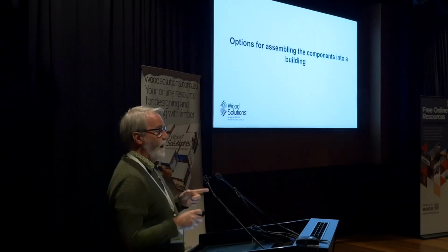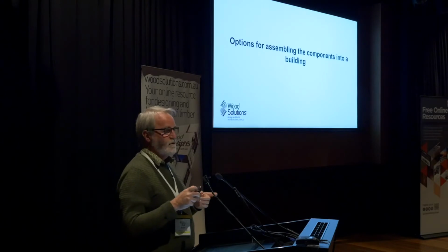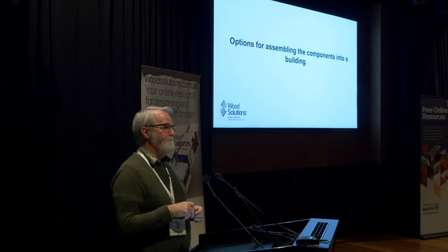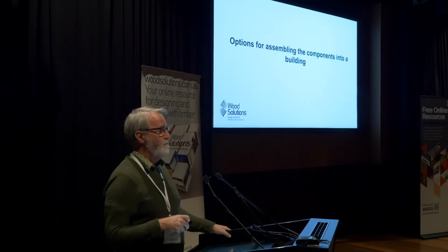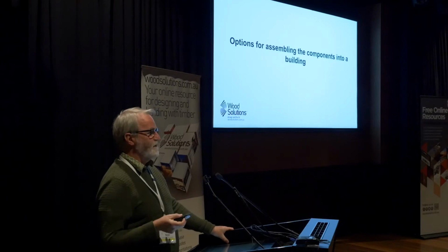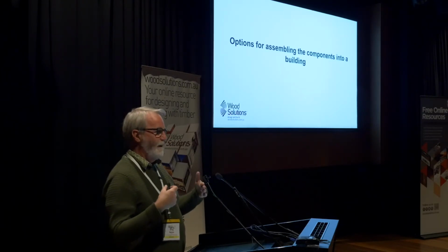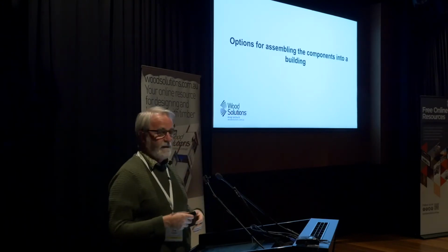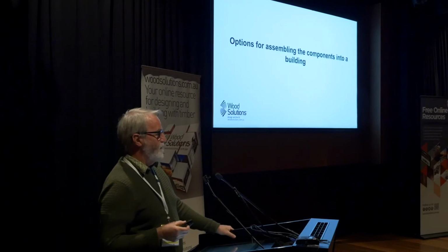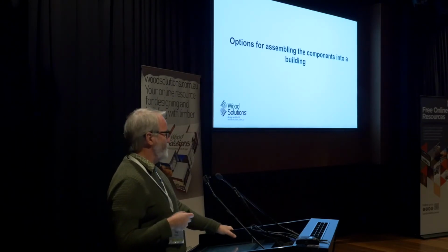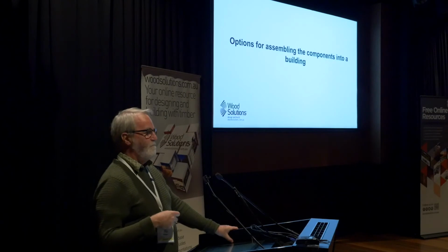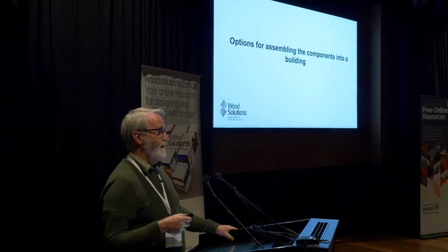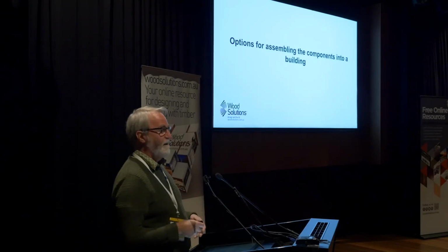We have attempted, wherever possible, to get basic structural characteristics for each of these materials in. So we actually do have from one or two of the LVL producers some of their basic performance characteristics of their products, and we've sort of amalgamated them together to give you guidance. Some of the products though are almost impossible, so it's almost impossible to get what bending and stiffness is for some of the OSB products that are brought in Australia. So we obviously haven't included them, but we would have liked to.